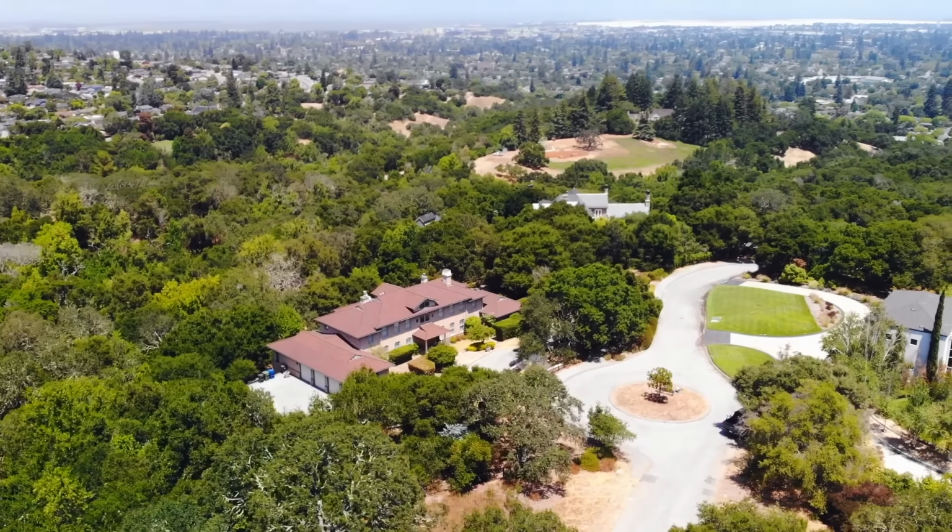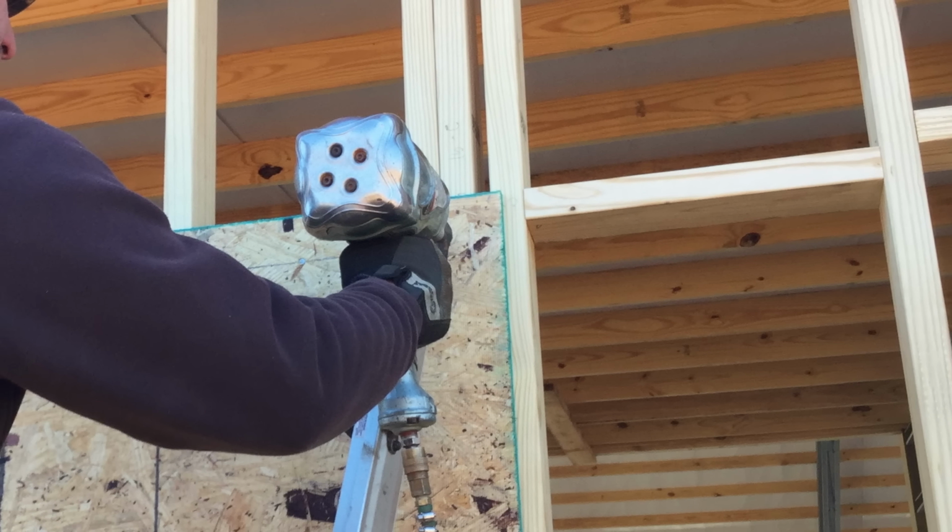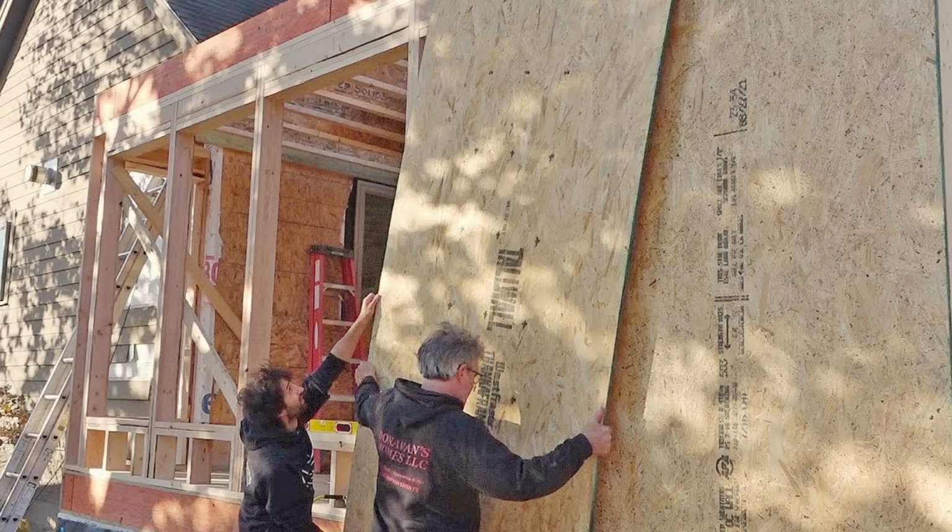So what does that mean to this house? Well, this house was built in 1990, which means that it matched 1990 code. Unfortunately, it only has 3/8 inch plywood on the exterior walls. That's not enough to meet the code for 2024. And so what we were going to have to do on this project is basically either tear off that 3/8 inch plywood around the entire house, removing plywood from the outside of the wall because it's not thick enough by 1/8 of an inch. Then we were going to have to take new 1/2 inch plywood and nail it to all the studs around the entire house. That is an enormous amount of work.